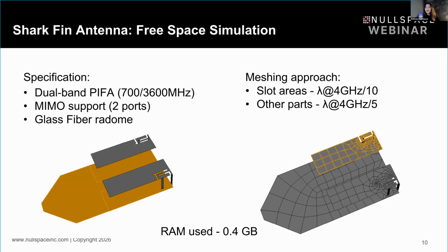Yeah, exactly. And I want to add that even with adaptive meshing, which we have in some tools, I myself, if I work with some other tools, still do some manual meshing. I need to have this control myself because the adaptive mesh is good, but I still need this control, especially in these kinds of tricky parts, where a lot is happening, a lot of currents. I really want to be sure that the mesh is correct. And if we move forward to the next slide for the results.